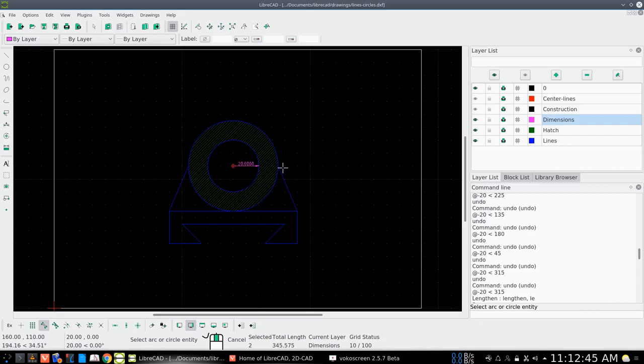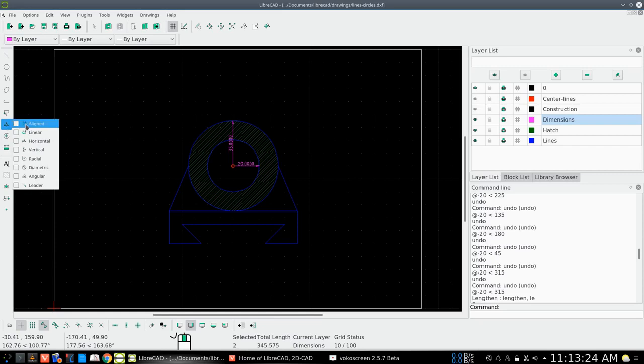So now it tells us to go ahead and specify another one. Now let's put on the free snap so we can move these dimensions around. Let's specify this arc. And the dimension line. You see, with free snap I can move that. Now you see we can put it where it's easy to read, perhaps. There we go. That tool's finished. Now let's go ahead and right click to release that tool, and let's get another tool. Let's go with aligned dimensions.